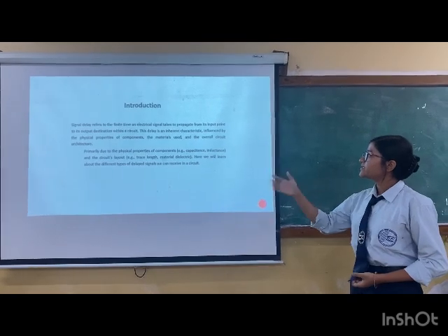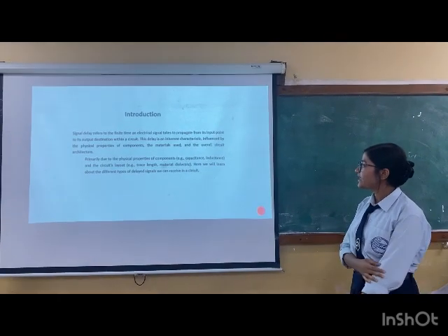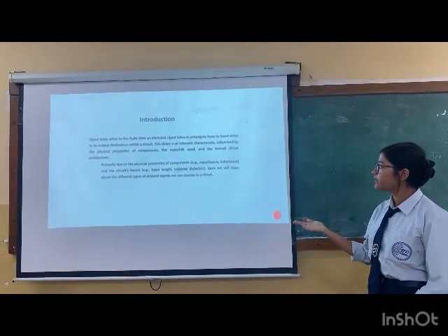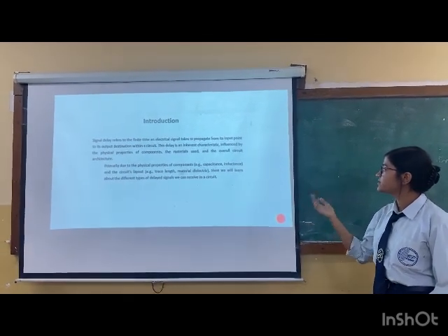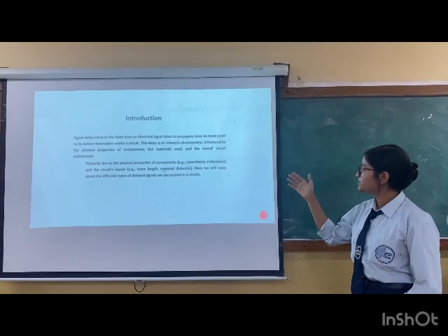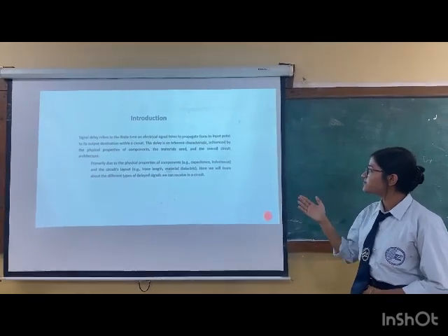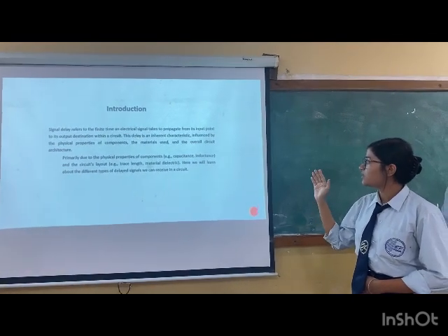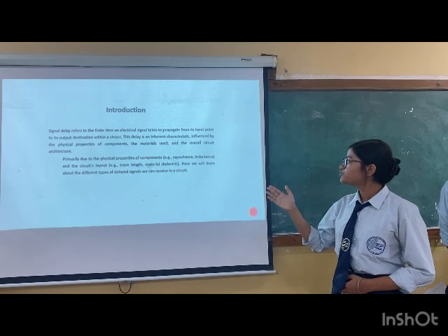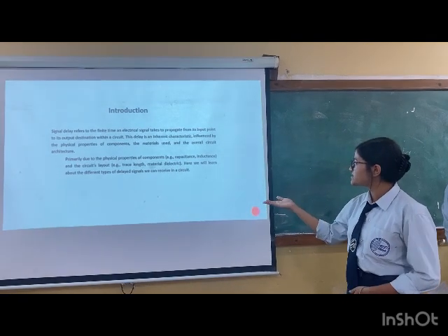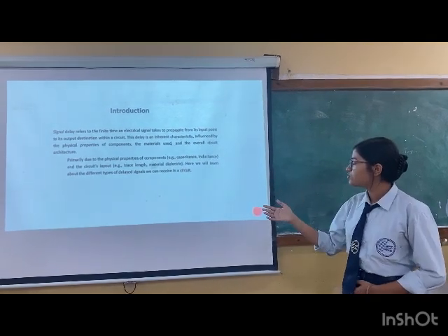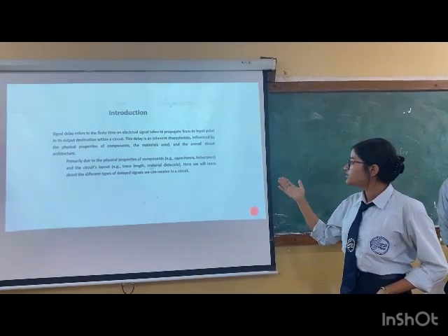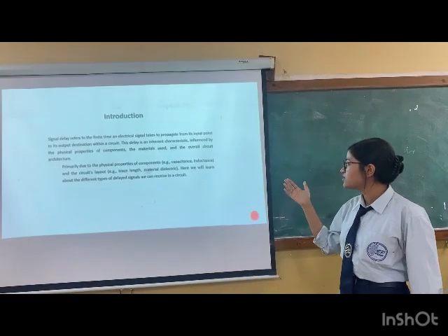So what is signal delay? Signal delay refers to the finite time an electrical signal takes to propagate from its input point to its output destination in a circuit. This delay is an inherent characteristic influenced by the physical properties of the components, the materials used, and the overall circuit architecture, primarily due to physical properties like capacitance, inductance, and the circuit's layout, the trace length, or the dielectric material. Here we will learn about the different types of delayed signals we can receive in a circuit.